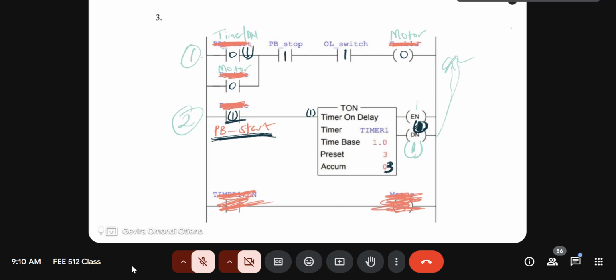But somebody mentioned something that's also critical. If we had other rungs, rung 3, 4, 5, then sometimes the order might be important because one rung was probably going to lead into another rung. But the way that our ladder diagram works in this case, between rung 1 and rung 2, there isn't really an important issue in the order in which we connect the rungs, because ultimately, we are still going to read through all the instructions, execute them, and then update the status after all the rungs have been exhausted. Okay, so it's not really having any effect.